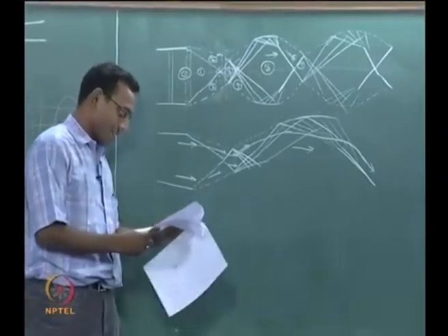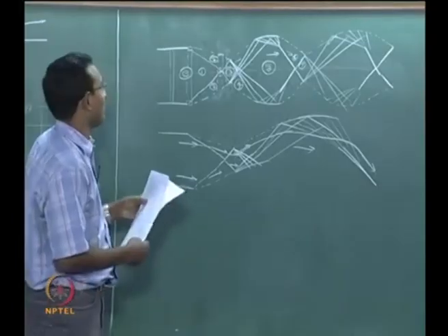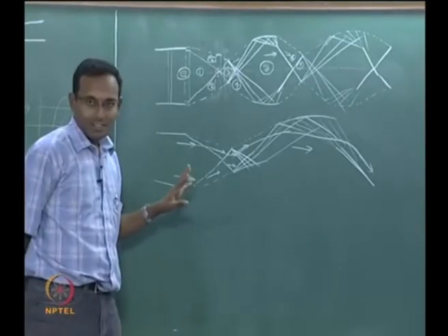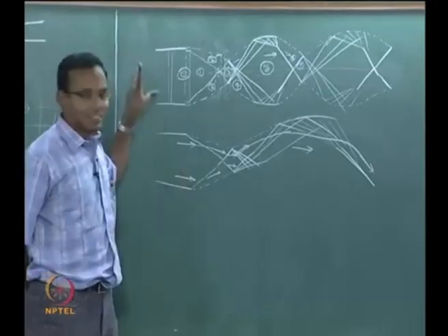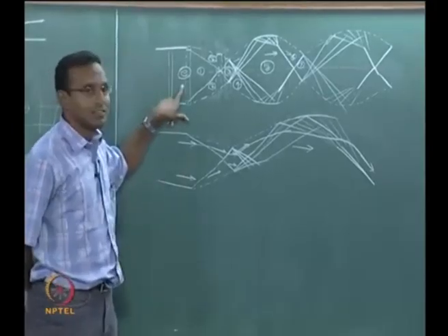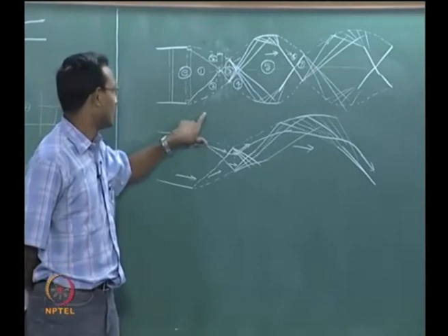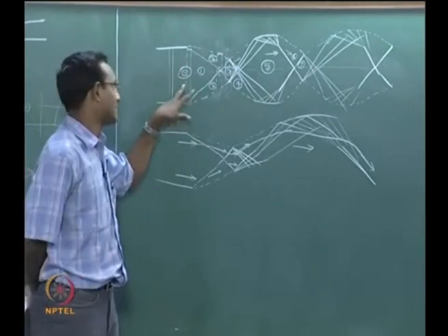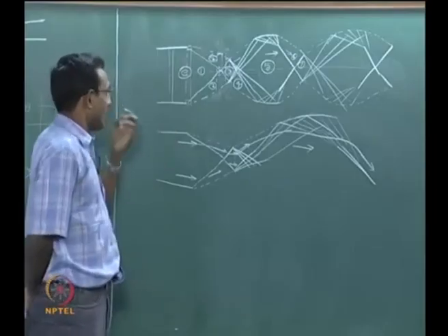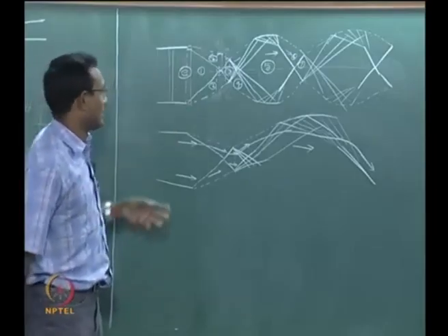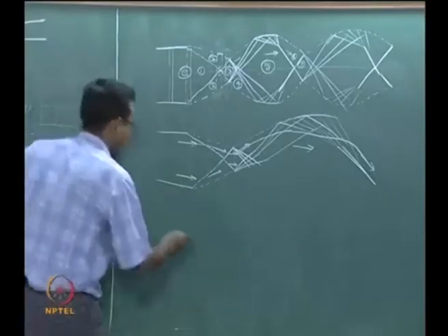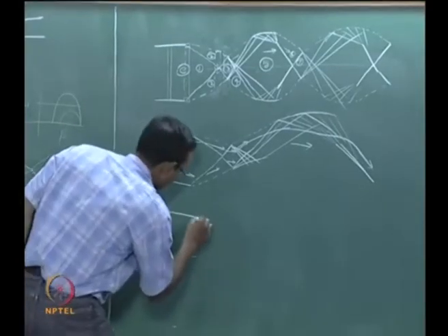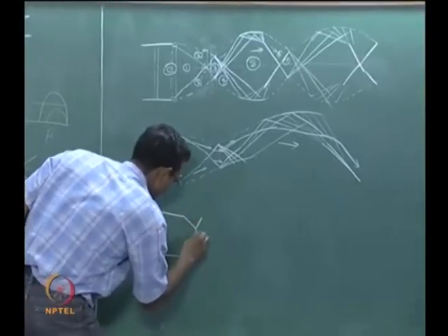Okay. Anyways, so we have come to a point where we have discussed to a reasonable extent over expanded jets, that is the cases where exit pressure is too low compared to the outside pressure, too much expanded, over expanded case. Okay. And now you can tell what happens in a more special case of slightly less than P critical 2 only, then I will have a case like this.